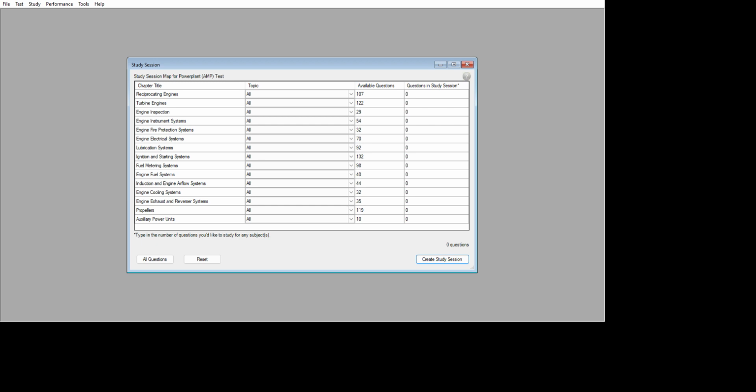Where are the high and low pitch stops on the Hamilton Standard two-position counterweight propeller located? In the counterweight assembly. Which of the following is used to correct horizontal unbalance of a wood propeller? Solder. Propeller blade station numbers increase from hub center line to tip.